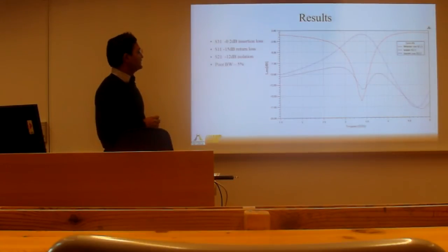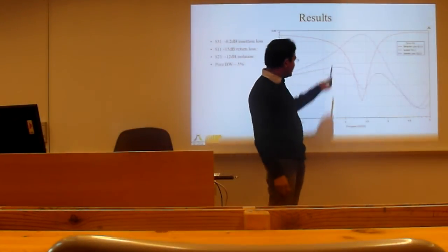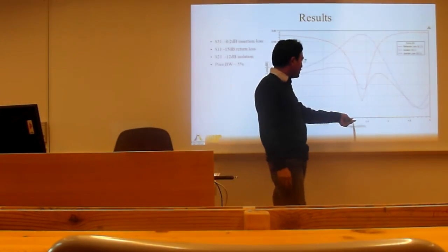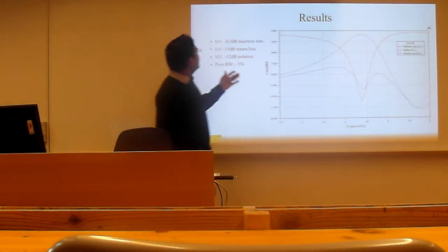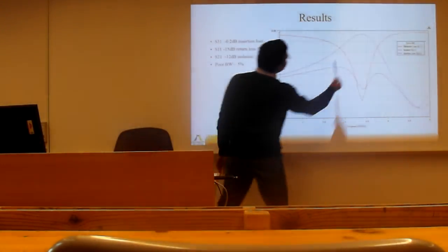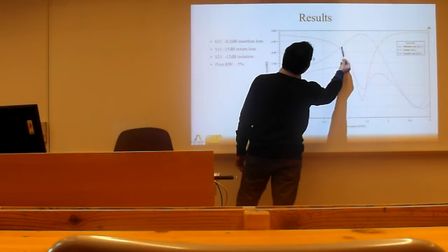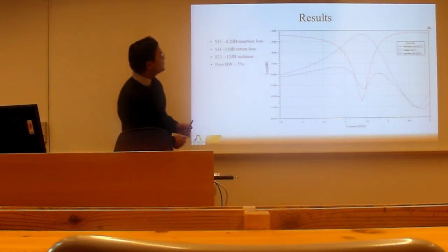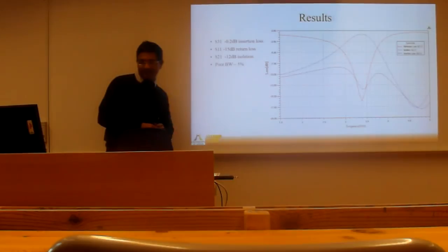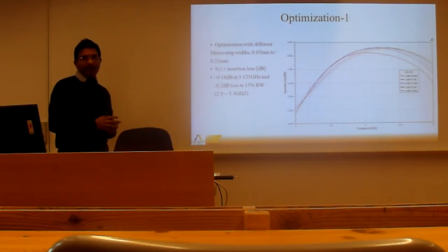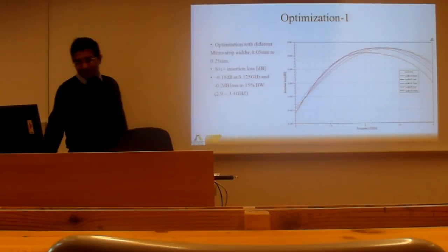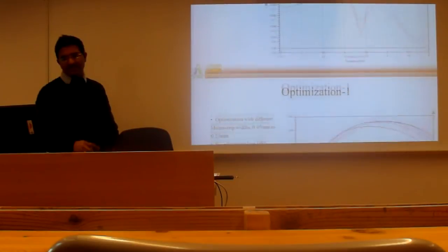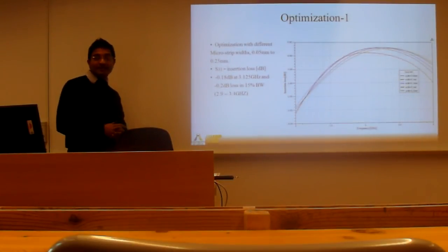The bandwidth is 5%. Yes, this is a very poor bandwidth. 5% is maybe 150 megahertz. When you consider this operating frequency, it is very poor. The upper cutoff you can choose is somewhere over here, like 3.1 or 3.2, and for these three S parameters it will be about 5% of the operating frequency. So the results we have obtained for every design are not enough for this communication application. Those S parameters are not enough.